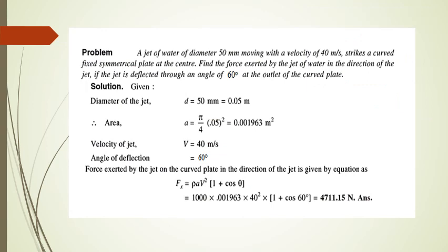Now let us do a problem on curved plates. A jet of water of diameter 50 mm moving with a velocity of 40 meters per second strikes a curved fixed symmetrical plate at center. Find the force exerted by the jet of water in the direction of jet if the jet is deflected through an angle of 60 degrees at the outlet of the curved plate. Given data. Diameter of the jet d equal to 50 mm. Now I am converting 50 mm into meters, that is 0.05 meters.